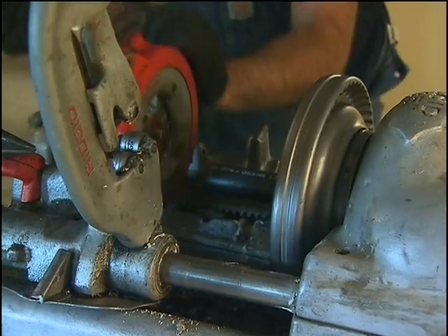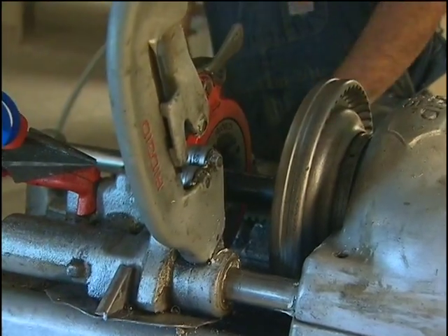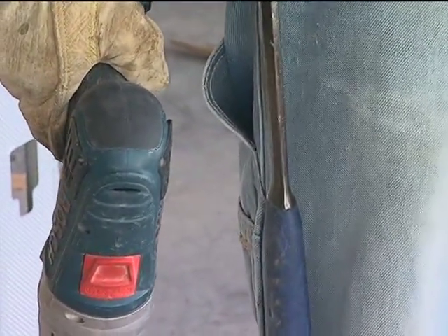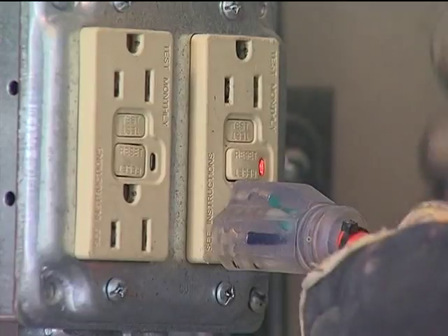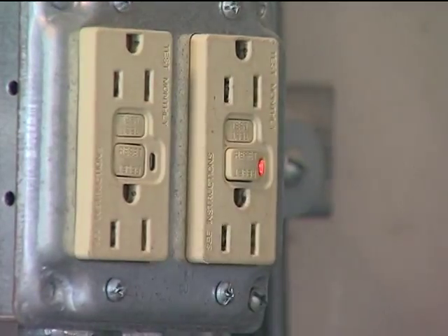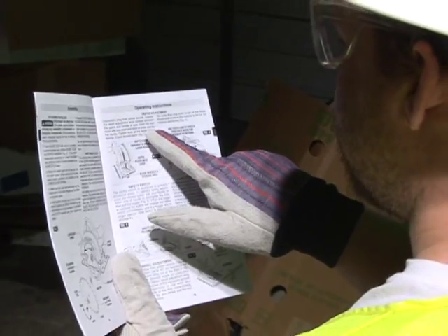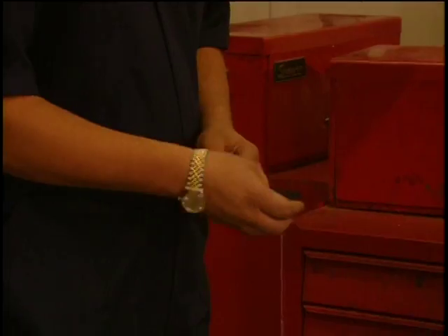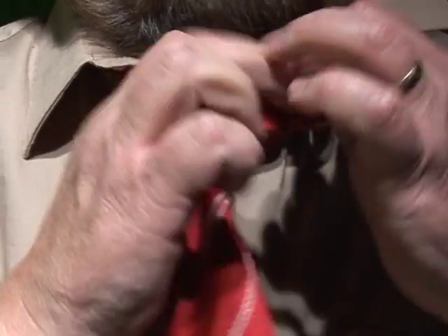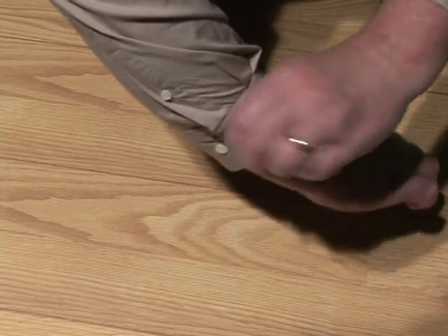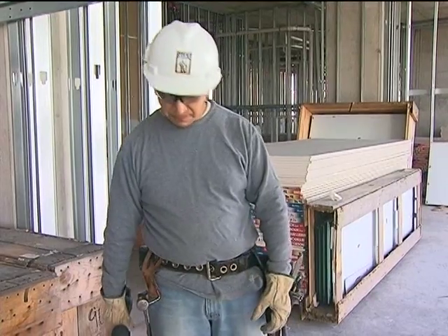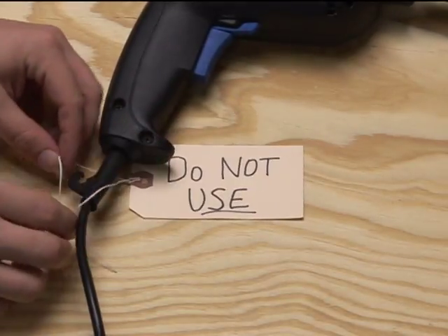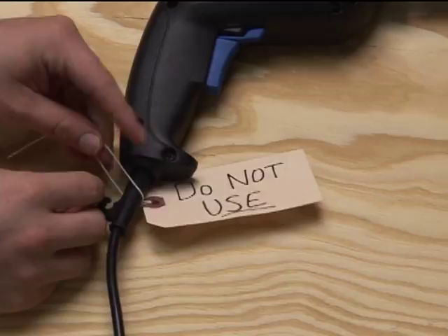When practical, always secure work with clamps and/or a vise. Avoid accidental starting. Do not hold your finger on the power switch button while carrying an energized tool. Unplug the tool if you need to move it to a new location. Follow manufacturer's guidelines for lubricating and changing accessories. Wear proper apparel for the job. Remove loose jewelry, ties, and button-down long-sleeve shirts prior to using any power tool. Loose clothing, ties, and jewelry can become caught in moving parts. Remove all damaged power tools from use and tag "Do Not Use."